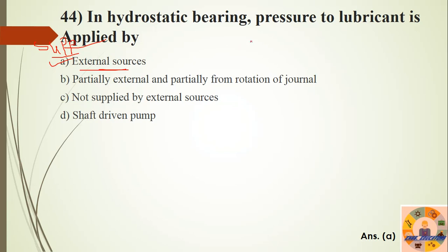Thick film lubricating bearings are two types: hydrodynamic and hydrostatic. In hydrostatic, the load supporting film separating two surfaces is created by an external source like pump.